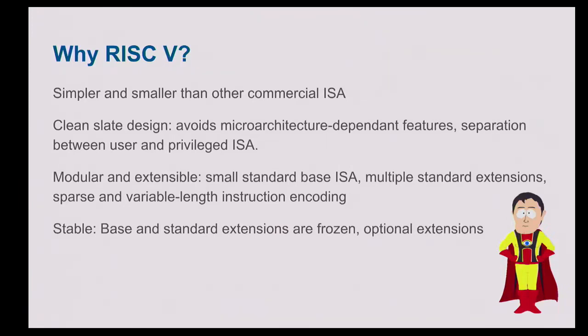It is modular and extensible because it has one standard basic ISA, and for all other purposes it has extensions. What is important is that this basic ISA and the extensions are frozen. Once they are published, they cannot change. So it is guaranteed that if you write a program for a current CPU, it will work on a CPU in the future.